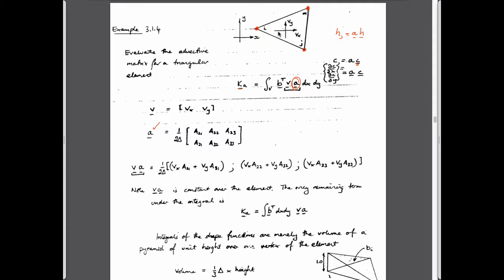We are going to assume that within the element we have velocities which are constant in each element. They aren't necessarily constant in adjacent elements, but they are constant within an element. And if we have those, then the product of these two we can straightforwardly get just by multiplying these two matrices together. These are just 2 constant values.